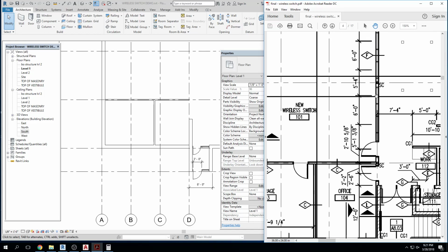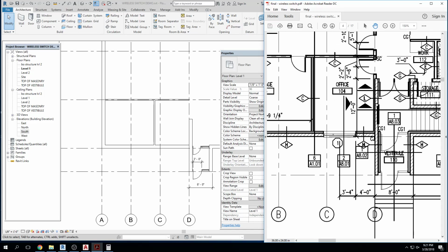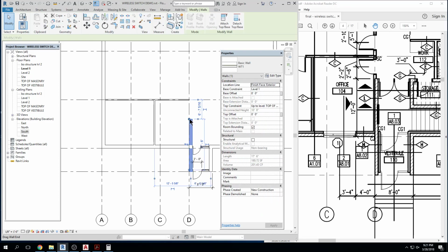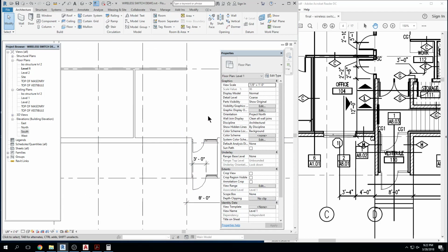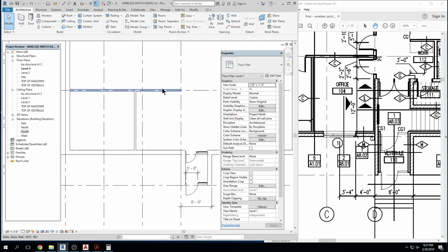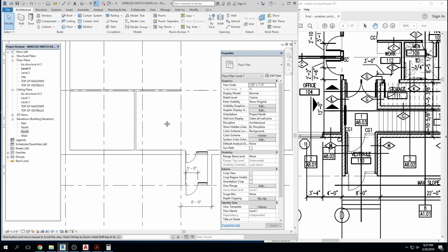And it looks like we have this framed wall. It's going to go midline all the way up to the end, so that's at grid line D. I think I'm just going to follow my first instinct, even though we're not doing this for real. So we'll just draw it. But when something looks like that, we always pay attention, because usually there's a reason why this is happening. Probably this is a fire rated enclosure right here with the stair and everything, so we don't want to just get rid of the block.